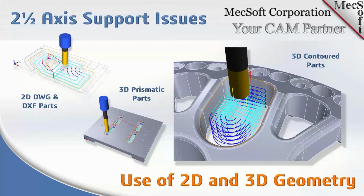And to do that, it's very simple. You just select your geometry like you do any other geometry. In this particular picture, you see that our control geometry is not flat. It's not 2D. You don't have to select control geometry that's on a flat plane. You can select any area or perimeter, and the program will flatten it out for you in the background. It'll do it automatically.